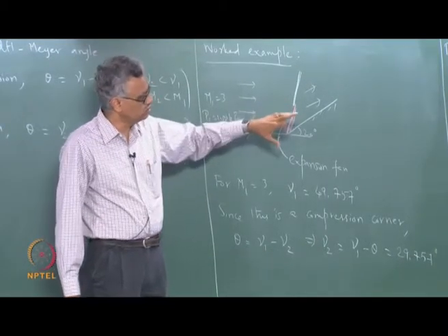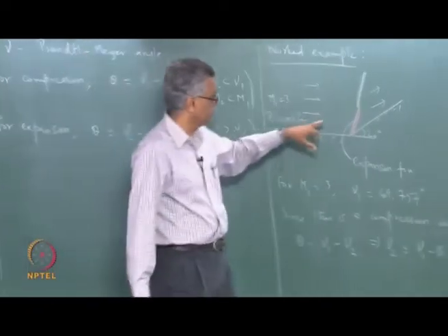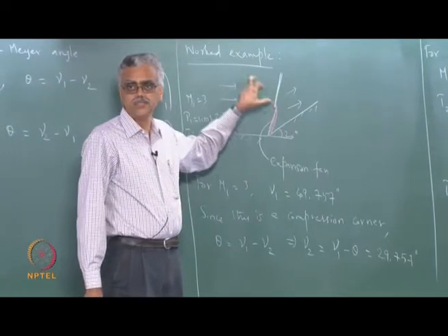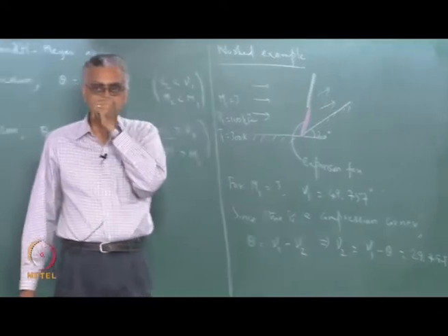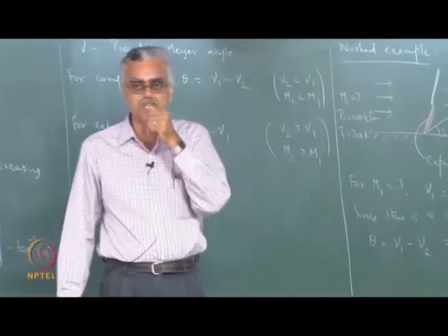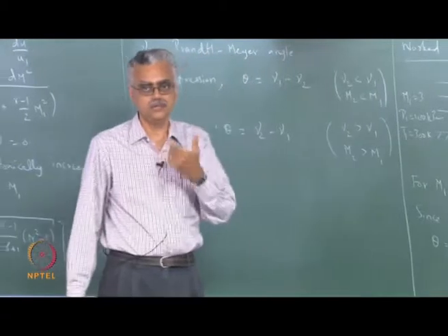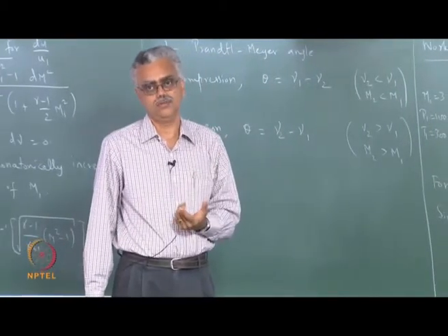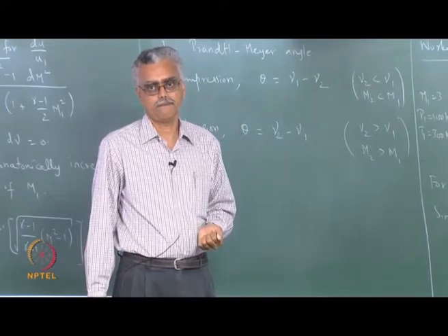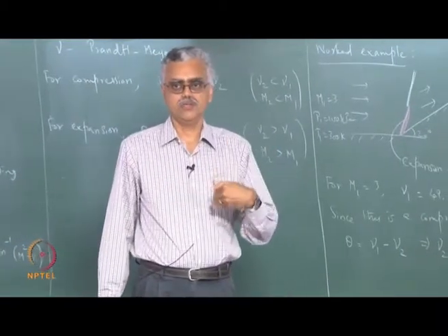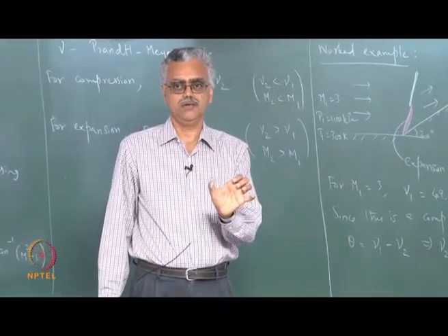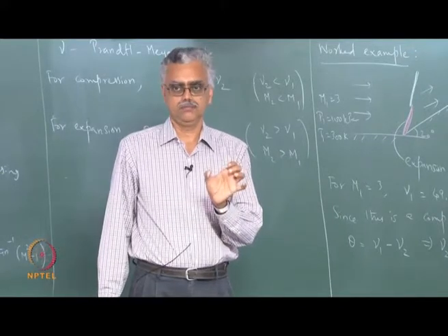Yeah, so static, we are considering static, it is independent of that is correct. No, that is correct. But what I am saying is this is fully isentropic. This is not a normal shock. The curves that we drew earlier were for normal shock. So for an oblique shock, whether it will hold or not is something that is not really straightforward. So it can happen this way. For normal shock, yes, the normal shock always gives you higher values of pressure and temperature compared to isentropic compression for the same change in specific volume.